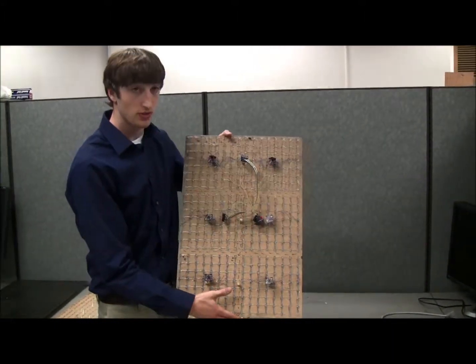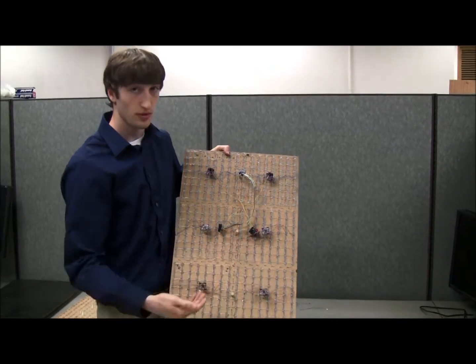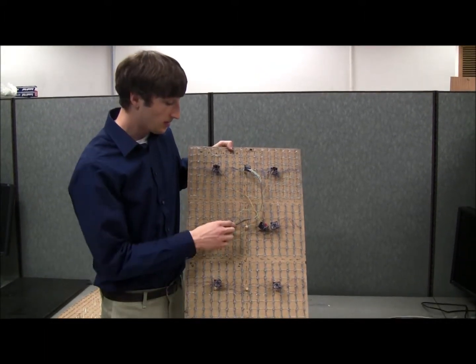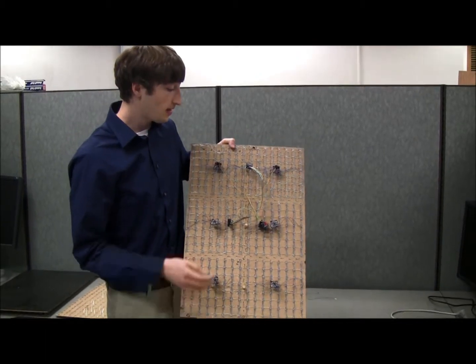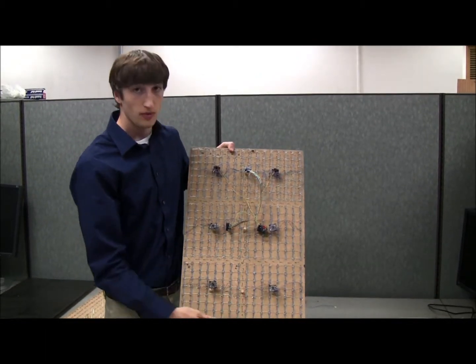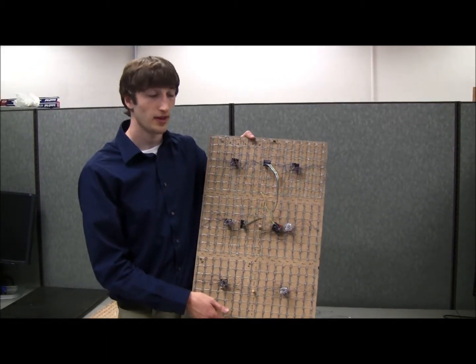There are 6 LED drivers here and here. There's a microcontroller that controls everything, and there's a shift register allowing us to multiplex through 8 different rows at a time, and there will be 3 different boards with transistors on them to allow us to source the current necessary for the different LEDs.